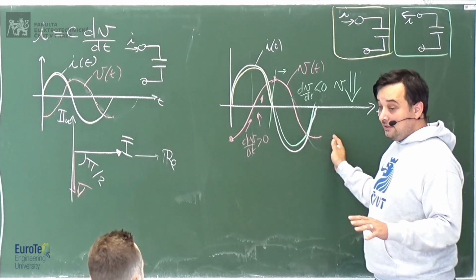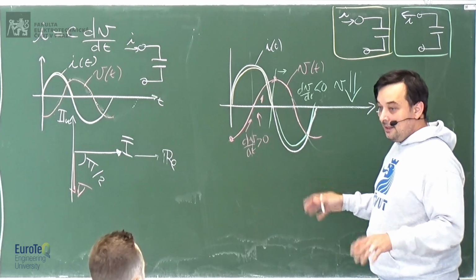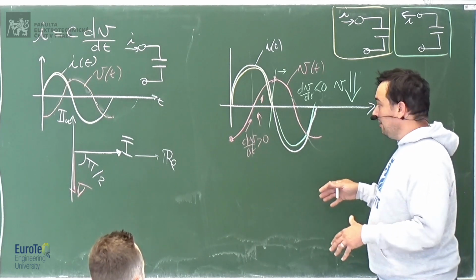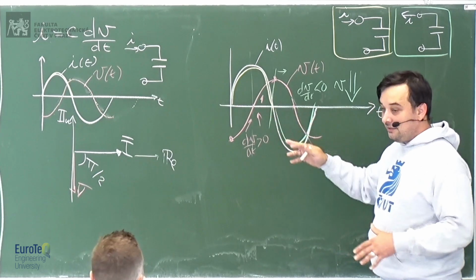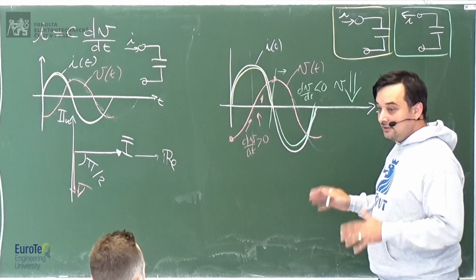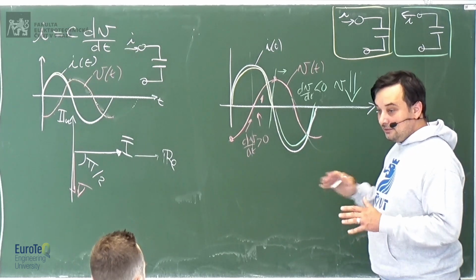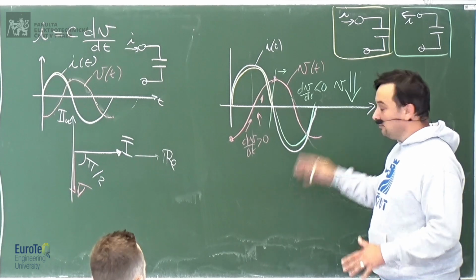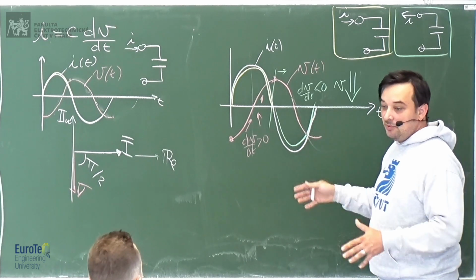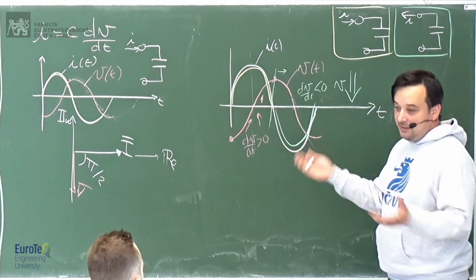The voltage cannot change instantaneously, but it will change smoothly because you have the derivative. But the current, yes, nothing prevents you from changing the current instantaneously and giving, from time zero, a current to the capacitor. So you start with a voltage which is zero and with a current which will be given by the condition of the circuit. Then we will see an example later.